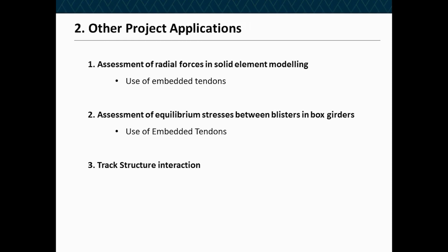ground-bearing slabs. And the interface element side of things is something that's a fabulous tool, because how do you model the relationship between two different materials when they're not mechanically connected? So to be able to have an infinitesimally thin layer, if you like, within your model, where you can give that layer a behavior, it's a very, very powerful tool for some of the more unusual analyses.